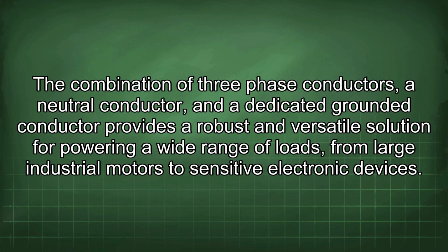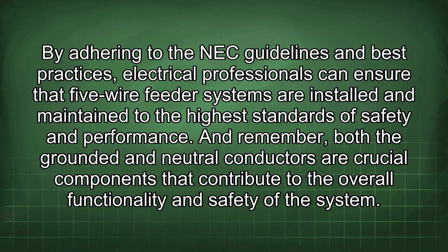The combination of 3-phase conductors, a neutral conductor, and a dedicated grounded conductor provides a robust and versatile solution for powering a wide range of loads, from large industrial motors to sensitive electronic devices. By adhering to the NEC guidelines and best practices, electrical professionals can ensure that 5-wire feeder systems are installed and maintained to the highest standards of safety and performance.